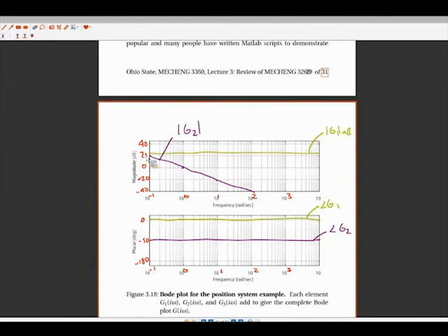Okay, so this means that magnitude, this goes in for low frequencies, 0 decibels, all the way up to a frequency of 4 radians per second. And then we're going to break down at negative 20 dB per decade from there on. Phase goes from 0 to negative 90. Because of the rule of thumb, the phase for a real pole takes 2 decades to go from 0 to negative 90, and it's centered around that pole location. So what I'm going to do is I'm going to mark 0.4, that's right there, and 40.